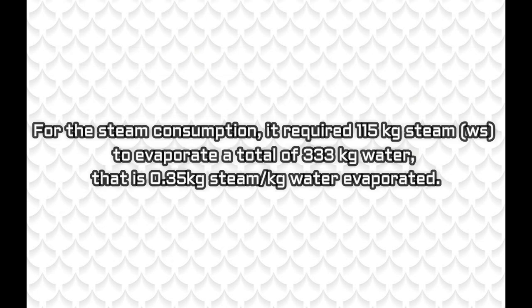For the steam consumption, it required 115 kg steam to evaporate a total of 333 kg water. That is 0.35 kg steam per kg water evaporated.